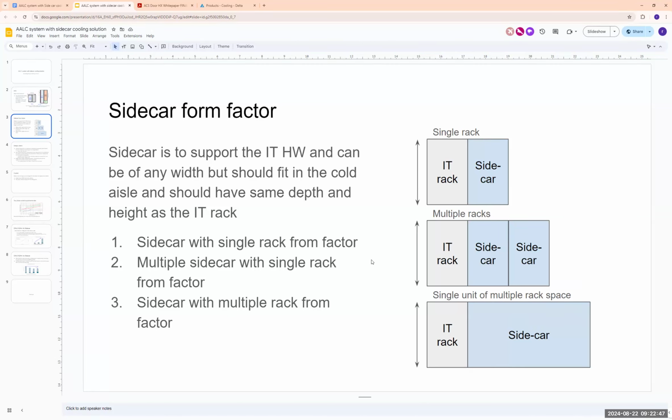Yeah, and the RPU does exist for every sidecar. RPU doesn't go away. If you have a heat exchanger, you need a reservoir and pumping unit. RPU is nothing but reservoir and pumping unit. That exists for every one of these, because without it the sidecar cannot function. That's the main pumping system. I think there might be a blurred definition between a CDU and a sidecar. A sidecar can be a CDU, but not all CDUs are sidecars. Okay. Yeah.